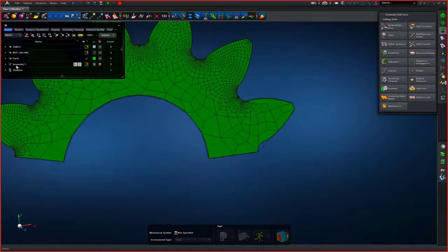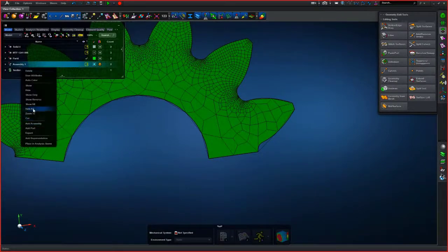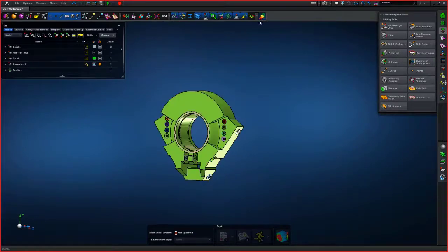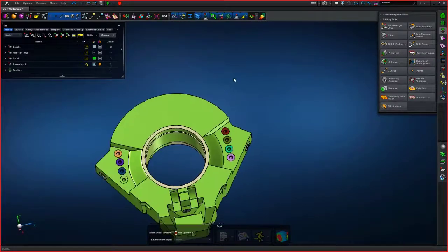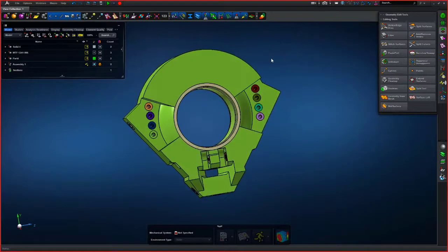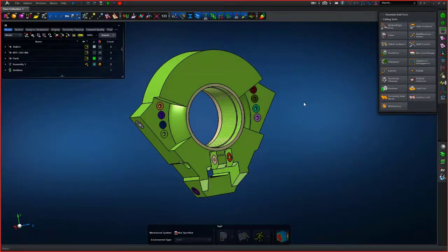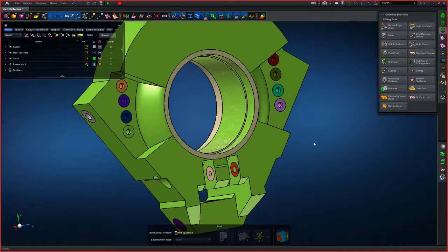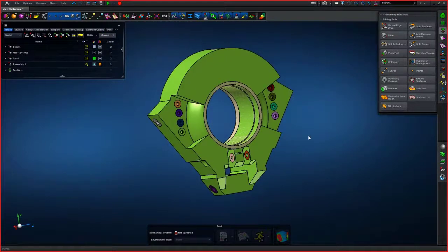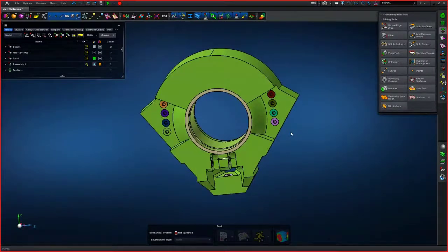And then the last example. Okay, definitely not going to hex mesh this guy at this stage, but let me show you the reason we would want to use partitioning. Now, in the new Apex generative design, partitioning is of particular importance because that is the way that you will be applying loads to this design space body and to get it into a generative design.